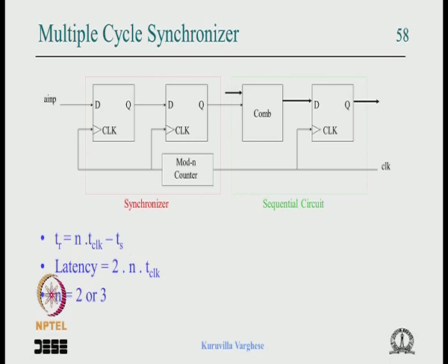But I said there is an issue here of skew, because there is a skew between this clock and this clock. The source register's clock is a delayed version of the destination register clock. So if you put the destination clock like that and the source clock is coming delayed, that will eat into the available clock period.